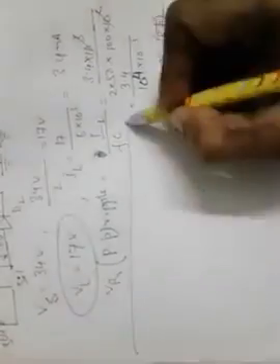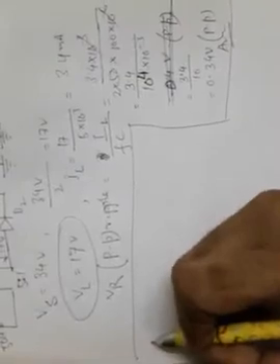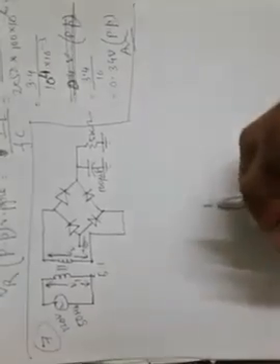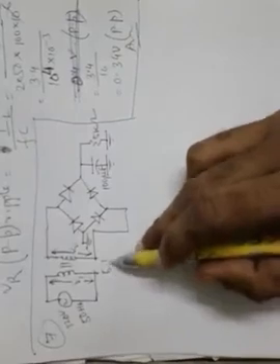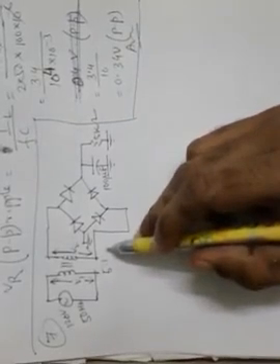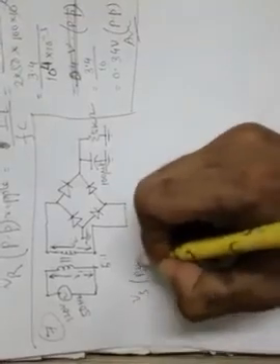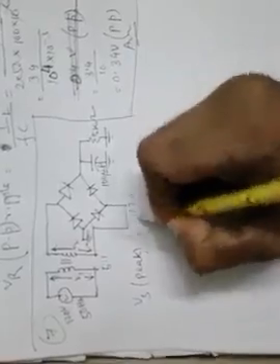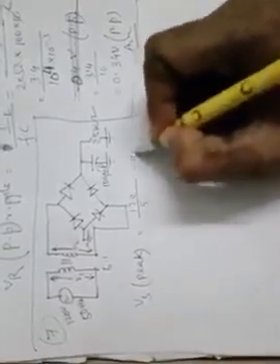Now let us see the last problem. Solve the same problem, problem number 7, with the help of a bridge rectifier. So here the circuit is of bridge rectifier, and we will be calculating the same thing, the DC load voltage and the ripple voltage. Since it is also the 5:1 step down transformer, as per the previous example, we will still be getting the peak secondary voltage Vs.